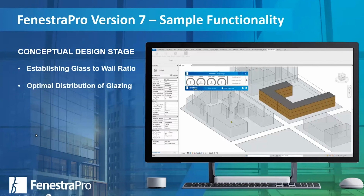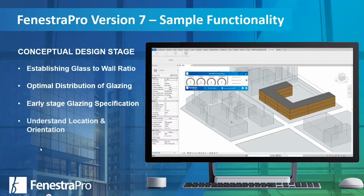of the individual facades. That early stage glazing specification gives you an idea of how those criteria can be controlled by material specification or material selection, particularly around the glass, but also around the U value or performance of your opaque elements. Again, understanding the location, orientation, and in fact, the variation based on inclined planes. For example, if your facade is at an angle, there's a different solar load that affects the passive solar heat gain calculations, and all those things are considered.